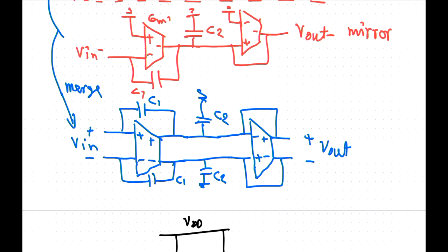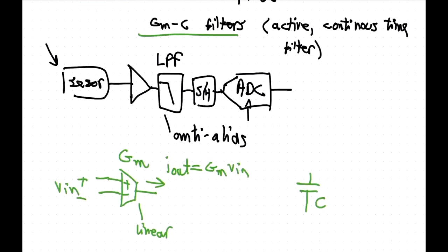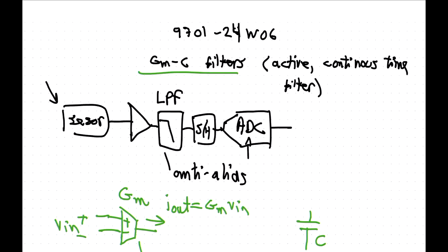Yeah? So if we go back to this one here, this is a very typical application where you want to low pass filter what comes in before you sample it. Then you will probably know what your sampling frequency is, and then you might know how many bits you have in the ADC, and you know something about the input. So you can work out how much attenuation you need for anything being folded back into the signal band. Now with that, you can then choose the pole and the order of the filter.